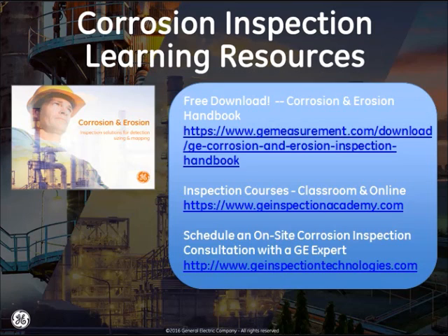Johnny, I have two additional questions that came in chat that are seemingly related. The first one is, can we offer anything for oxide scale measurement in the range of 50 to 100 microns? The second question is, what is the resolution and the minimum size measurable with RX technique? Can you speak to those, please? When you're looking at scale or some type of build-up, typically you would use X-ray as a screening tool, and we can definitely use the wall thickness measurement tool to take a measurement.